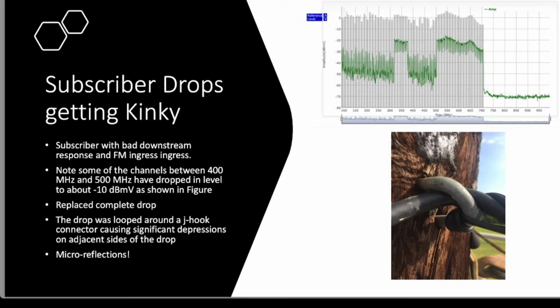We got macroblocking. Basically, we get a subscriber calling in and complaining about their service. We looked at the root cause of this and found that this was a bad drop. So again, we're talking about bad drops, specific individual subscriber issues. Some of the channels between 400 and 500 megahertz had dropped in level to as much as negative 10 dBmV. We replaced the whole drop, and what we found, as we're showing in the picture here, was